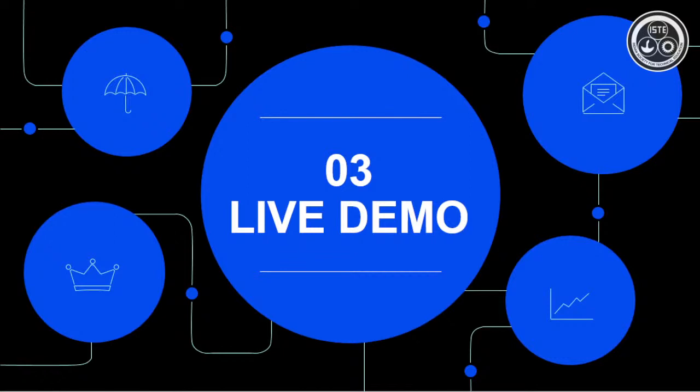So in the void loop, we will be giving code like: declare float t is equal to dht.readTemperature. As you can see, the words will automatically turn orange if it's correct, because these methods are already defined in the DHT library. We are just calling them using the object. Don't forget to give it a semicolon, and to read the humidity, again declare float h is equal to dht.readHumidity. It does not take any arguments.